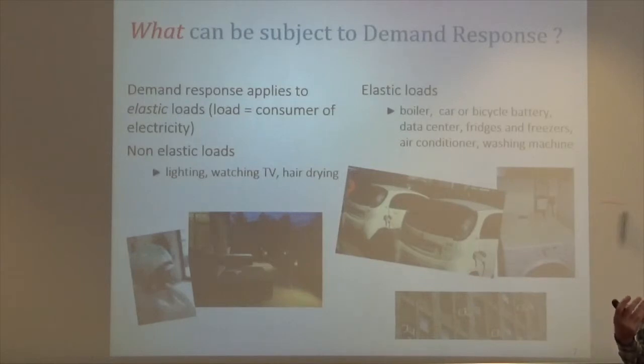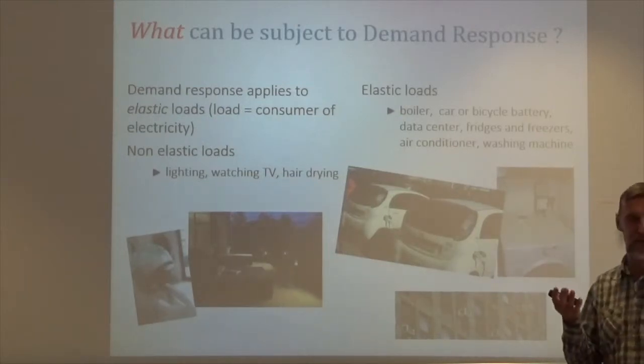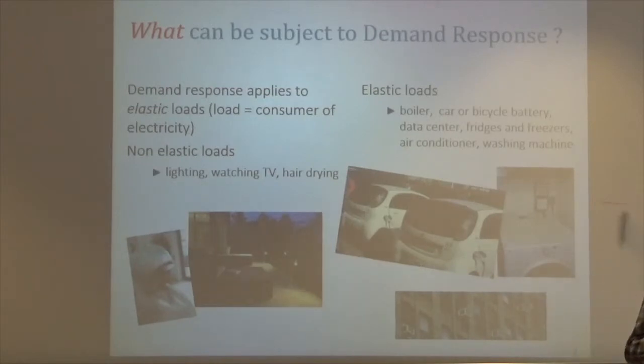So the electricity company have lost one of the technical means they use to adjust the variability of their production, which today variability is essentially due to forecasting errors. When there is, for example, a huge peak of consumption that was not forecasted, that's very rare, but it can happen. Or when there is a failure somewhere. You lose a generator or you lose a line. If you lose a high voltage line, you may have to reduce the power consumption in one part of the country. And one way to do that is to shut down, for example, all the resistive heating systems.